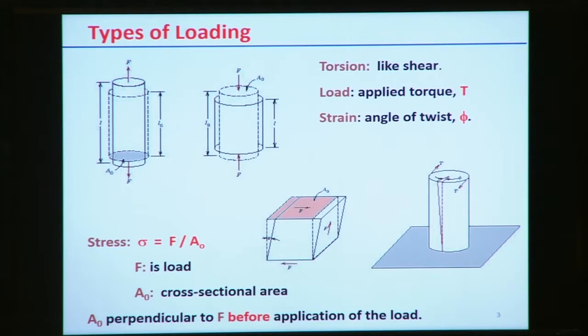Analysis of the stress. The generation of the stress actually depends on the type of loading. The load can be applied in different directions, and when you try to estimate the load, we can consider the area over which the load is acting at different orientations, and accordingly find out whether any normal stress or shear stress will be produced. Let us look into the different types of loading.